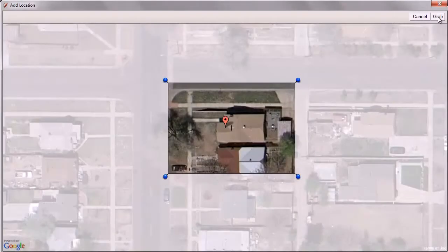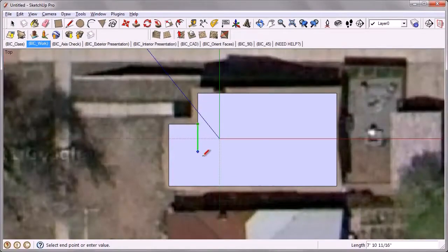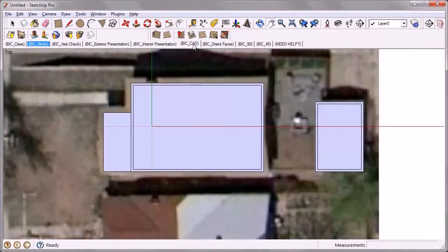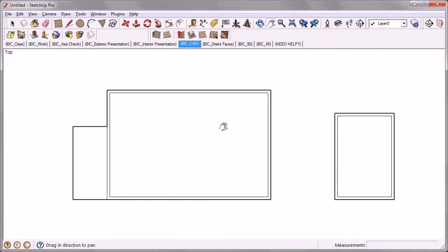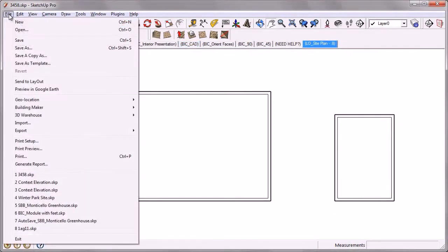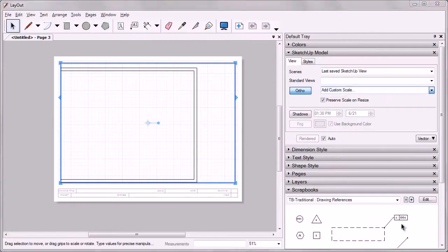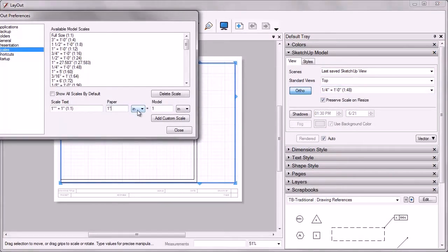Use SketchUp Pro to expedite as-built drawings. Aerial imagery allows you to pace off a building before even arriving at the site. Accurately scale and proportion 2D building outlines in minutes. This eliminates accidentally drawing off the paper while in the field. Set the building outline to a custom scale in Layout to maximize the use of your paper size.